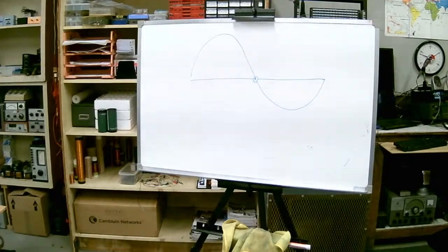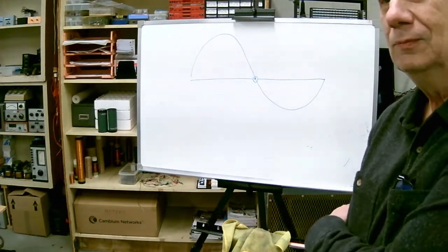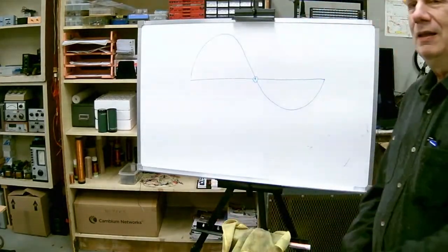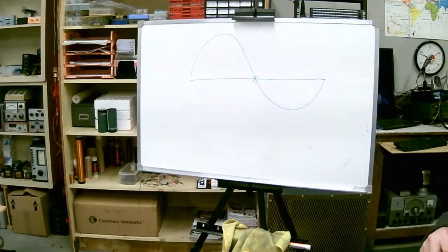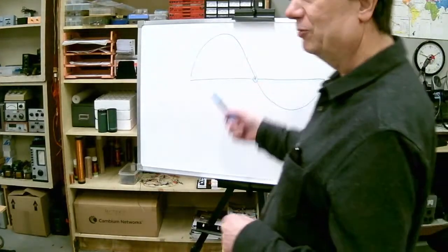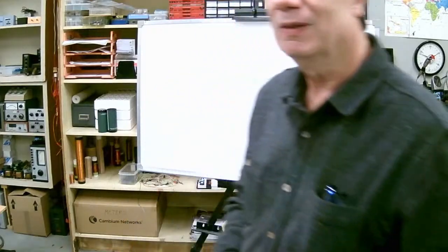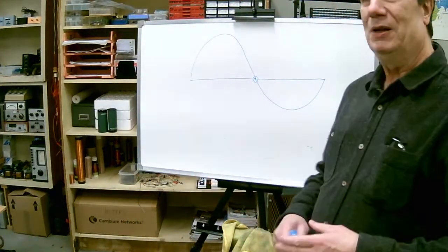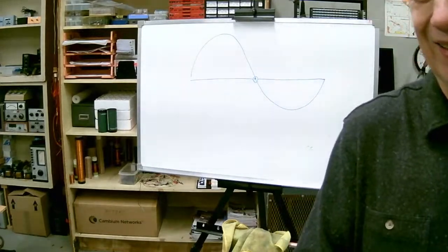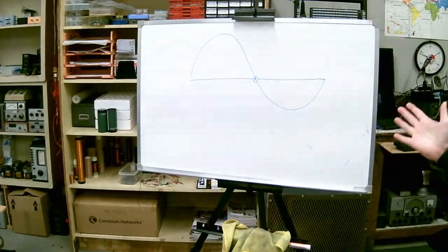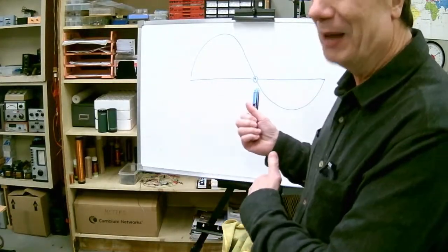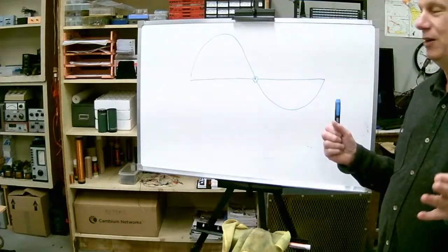If it's full length, wouldn't there be an issue with the dipole being at the middle? Well, the feed point is definitely going to be different here, because when we're feeding it where the current is maximum, the impedance is very low, that minimum being 72 ohms. This is going to be several thousand ohms at the feed point. So first of all, the feed point is going to be all squirrely. Now, it doesn't mean we don't use it. It doesn't mean it's a bad antenna. It's just that everything's going to be changed here.